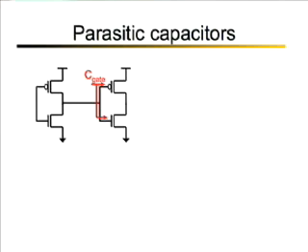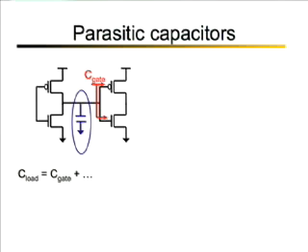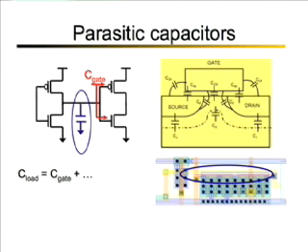So the parasitics should be lumped together, and we are assuming that the parasitics can be lumped together and provided as a lumped parasitic at the output node of any cell or any gate. So the total load capacitance that the inverter would see would essentially be the C gate, which is the gate input capacitance of the next logic stage, plus some other capacitors, which are essentially the parasitic capacitors. In our present simulation environment, we have captured two kinds of parasitic capacitors. The first one, let's look at what are the device parasitic capacitors that one can typically get in a MOSFET.